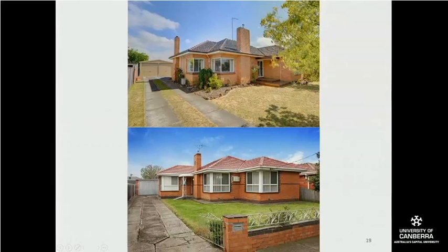So really the conventional uses of bricks are for houses, for cladding, for fences, and so on and so forth. You can see that all of these things work best in compression, and when you have these kinds of corners here, you need to support them with something else. Nowadays we have steel lintels to be able to hold up flying corners of brick. But in the old days, they used different methods, which I'll get to in a tick.